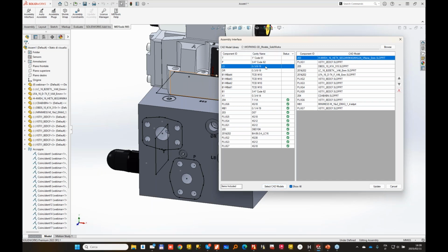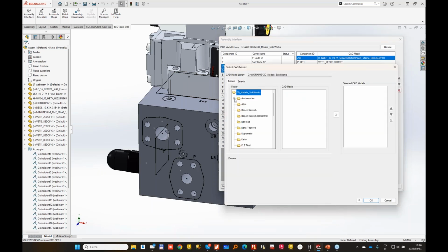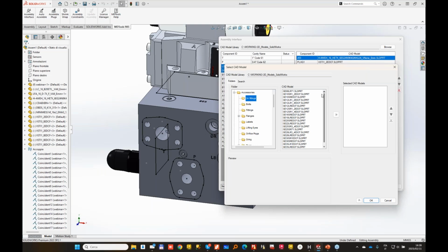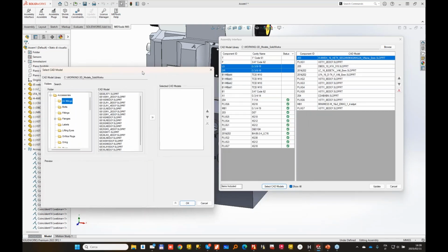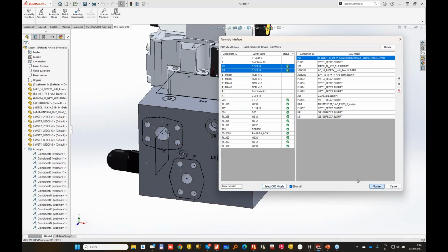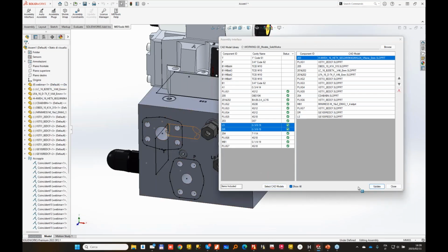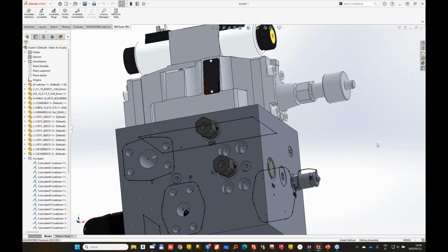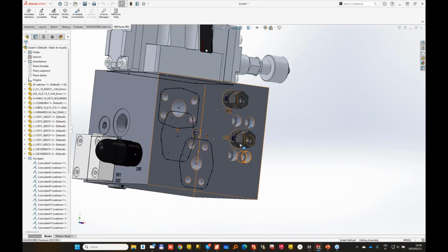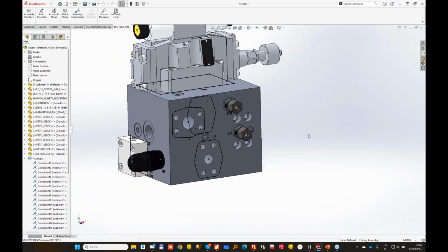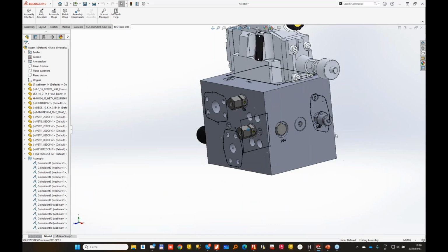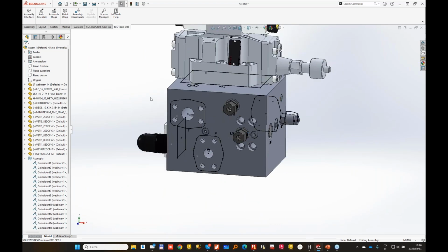What I can do with this assembly interface is, as an example, I could link fittings if I had not linked them directly into the schematic. So in this case, it's a 3x8 G10 SR, should be okay. And now I can assemble some fittings to the ports automatically. So drain port and load sense signal will go directly to something else somewhere else in the plant.